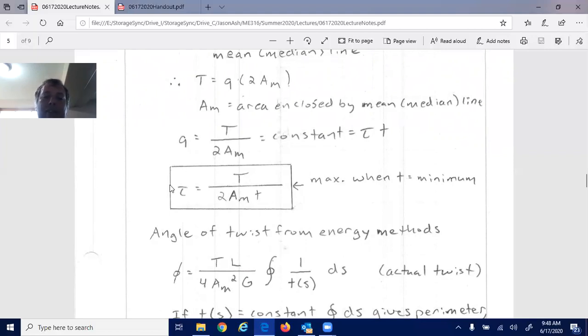And so it collapses nicely down into an algebraic form based off of that line integral equaling 2 times the mean area. And if you're dealing with routine cross sections, then it's easier to calculate that mean area. You really don't have to do a line integral at that point. Say if you're dealing with a rectangular tube, I can calculate the area of a rectangle pretty easily.